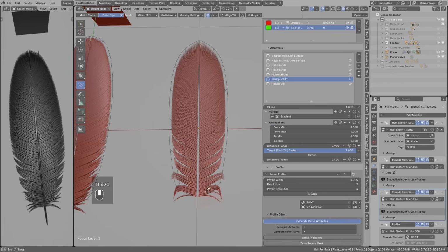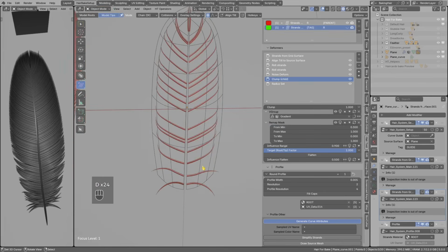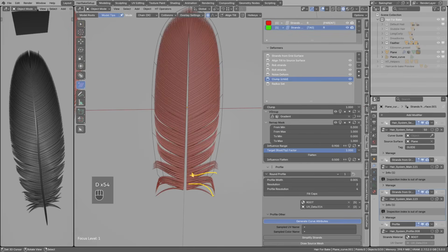Now the second part, this is more complicated to explain, but in general we have those red guides. And green strands are going like to the top, and then clamp effect kicks in, so it bends toward the red strand. So this goes like that, and then clamps overtakes the strand, and this is why we get this ugly bending. The workaround I found out was to just remove clamps effect from the first part on the bottom. So I will have to create a different kind of gradient for the clamp effect.